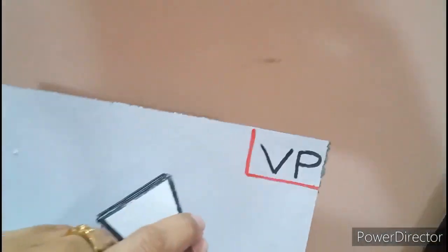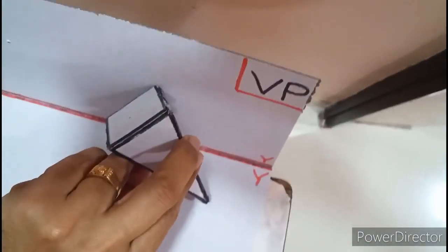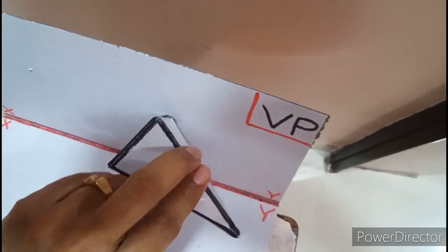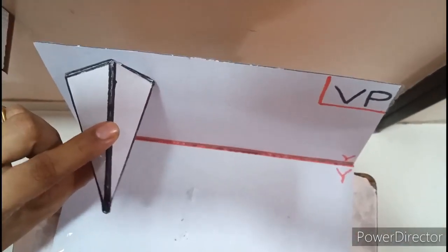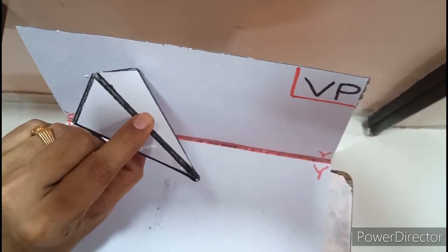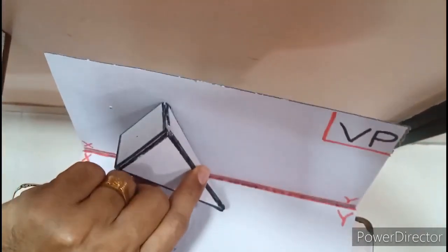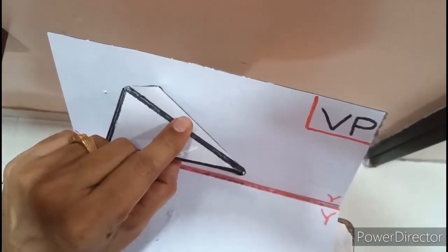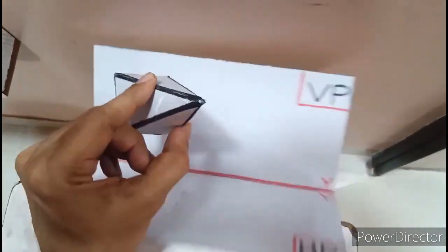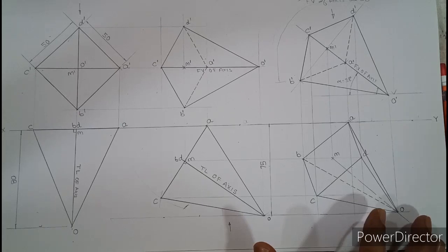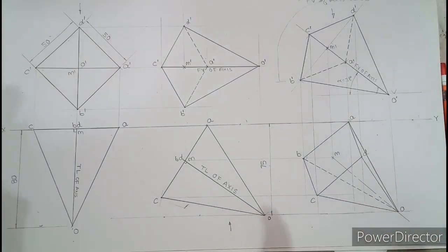Now if you look in the top view, some portion of the white base can be seen. So very simple. This was the first stage, top view. This was the second stage, top view. And when you now tilt and make the apex near to HP, you can see the base from the top view. Opposite, if the apex is away from HP, you cannot see the base. Okay, so by this, all the three views are over.